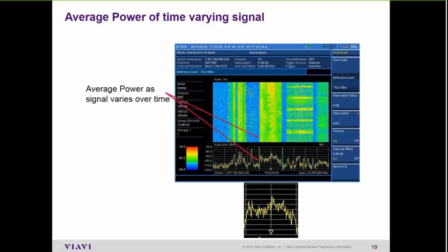So again, if you look at the amount of power that's being transmitted, if your average power is set to 30 dBm and you have this sort of crest factor, which is the difference between average power and peak power, if you go up 15 dB or 12 dB on this, that can be up to 100 watts difference between peak to average. So it's a varying time rate of power. So again, average power is really the way to make these measurements.